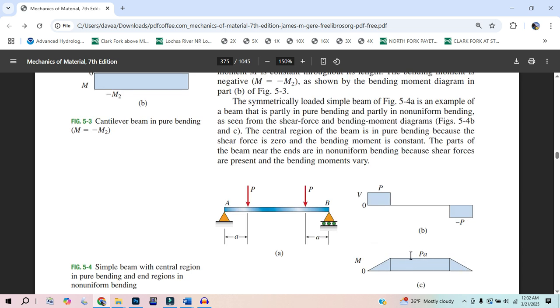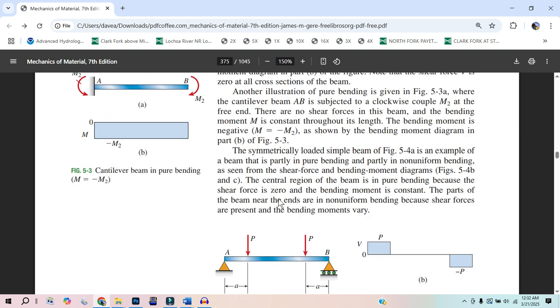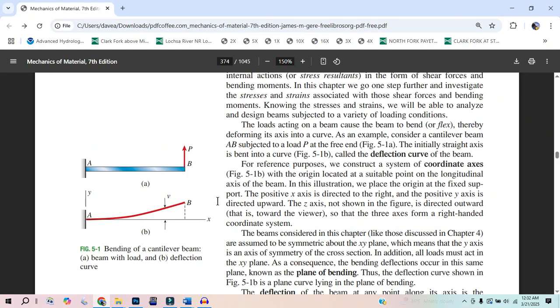Max bending is where the breakage is going to occur. So in this scenario, we're going to get a break somewhere between here and here, because those crunching stresses, those tension stresses are going to get to that 58,000 if this is steel, and we're going to get some sort of ripping along the bottom and some sort of crunching tears on the top, compared to this scenario.